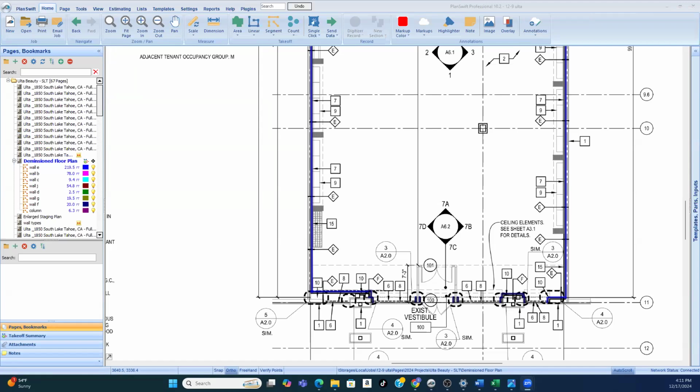Okay, so the A plans again, that's what this class is all about. Is everything that goes in and on the building once the building's been constructed. And so again, framing, we have to make sure we know if we're talking about structural framing, which is the roof joists, floor joists, columns, beams, headers, or the A plan framing, which is the floor plan, the ceiling, the reflective ceiling plan, the door frames, and all of that. So everything that goes in and on the building once the building's been constructed.